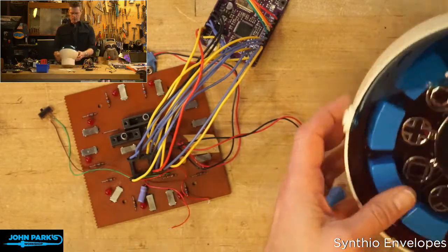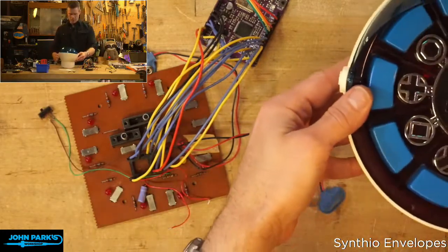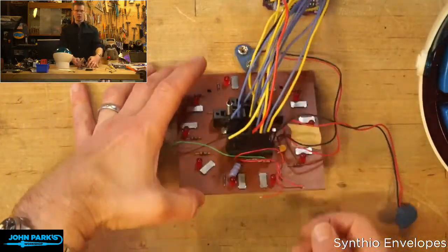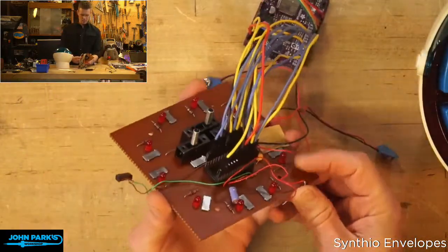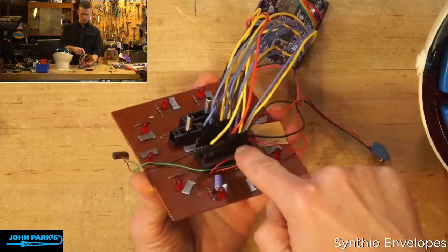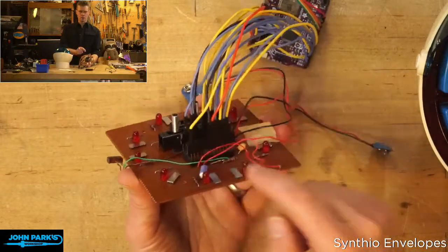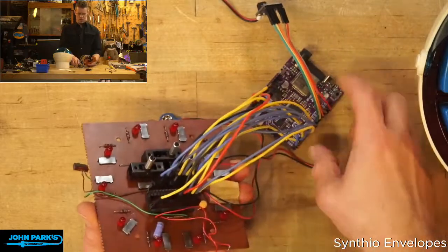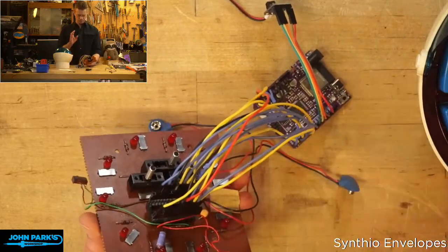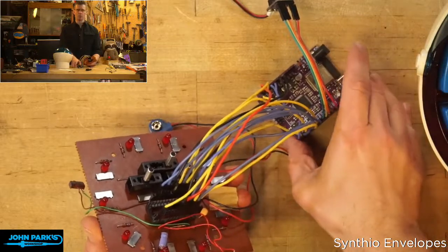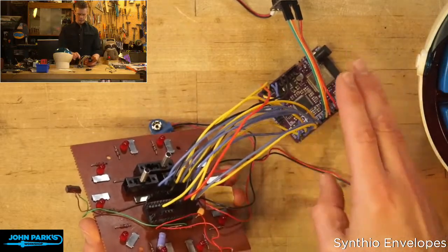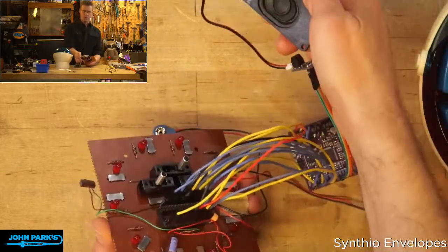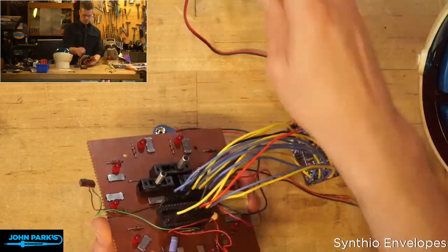So part of what I've been doing is I removed the IC, the original 4-bit microcontroller, and have been plugging breadboard wires into there to use these buttons and switches on my Metro M7. Metro M7 is running CircuitPython and the Synthio code, and then I'm also running a little I2C amplifier to one of these little speakers here.